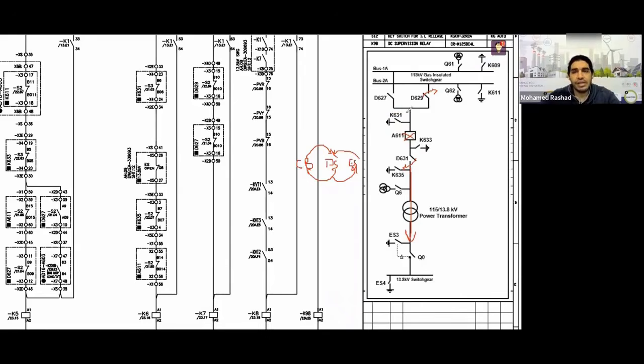I want to close this now. This side has a supply, and the upper side has a supply. Closing both together will work through what? Through my disconnector. So what's the solution? The solution is that I need to check the synchronization between the two. Now, if I check the synchronization between the two and then close the disconnector, during the 3 seconds it takes for the disconnector to move, what could happen? Slipping, which is a difference. All right, between this wave and that wave of the voltages, a difference will be generated.